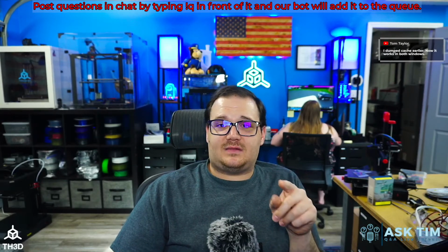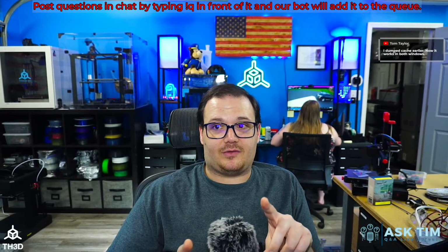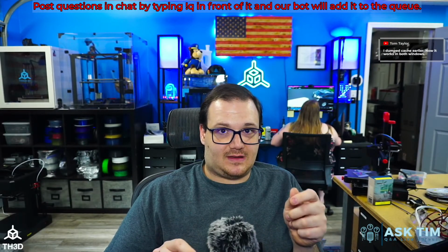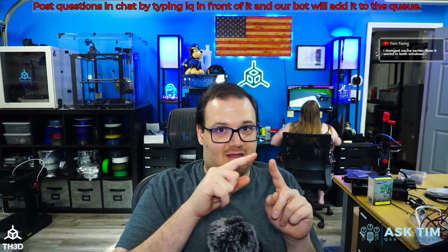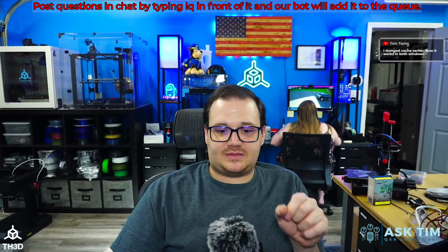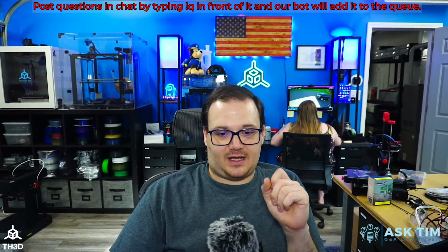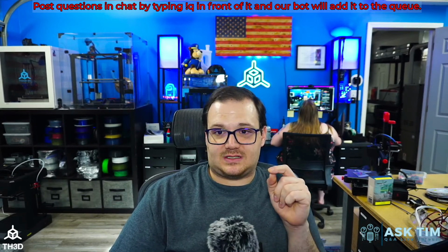But anyways, sometimes I've also seen it where they swap it at the motherboard side of the cable. So make sure you check both ends of the cable, because sometimes they're sneaky and they'll switch it at the motherboard side. But most of the time it will be switched at the motor side, but not all the time. You just got to keep an eye on things and be aware and track your stuff.